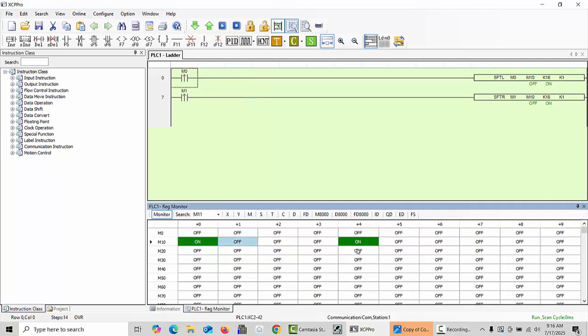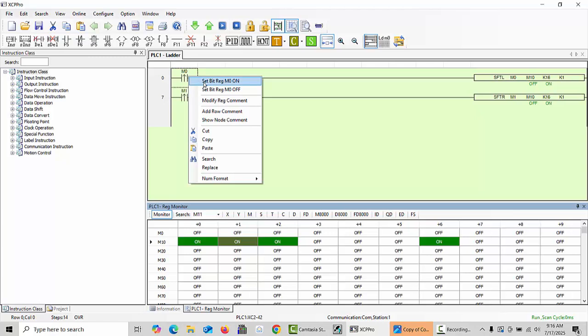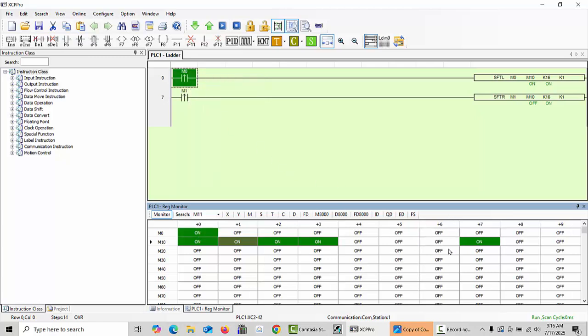So this way it continues up to 8 bits, on and off. But now we are only using it for testing purposes, because of the physical input signal. You can also choose X1, X2 from the field signal. Basically, this shift left or right command is used in the programs of filling projects and packing projects, working one by one, step by step. So next we will stop this one, and now we will check left to right.